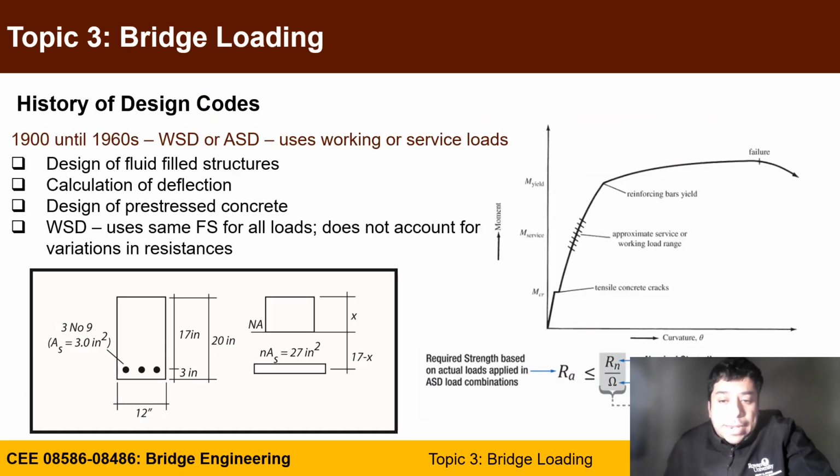We can go back now and touch base on design philosophies. The first design philosophy, from 1900 to 1960, was predominantly WSD or ASD, working or service loading. In this philosophy, if you have a structural element, we will use a safety factor, omega.